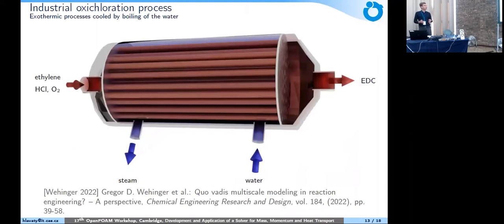The last application of the developed solver that I would like to talk about is connected with industry, in particular with the industrial oxychlorination process that is usually performed in these types of reactors, where a tube packed with Raschig rings with catalytic material is cooled by water evaporation.